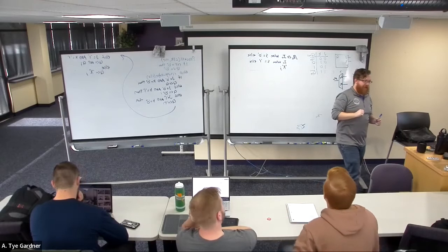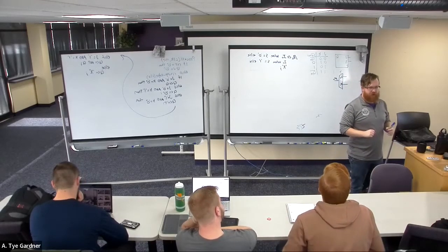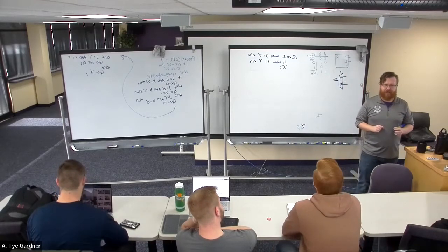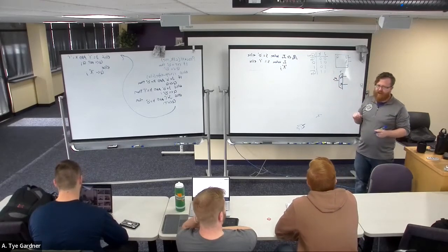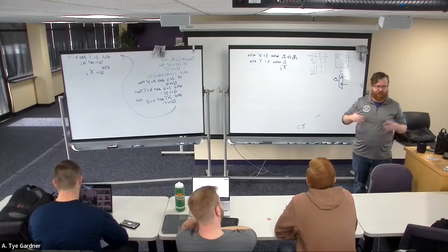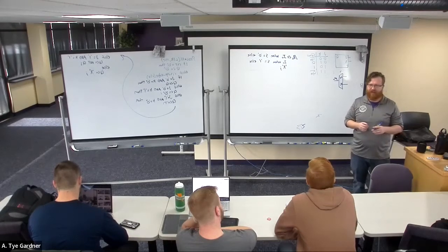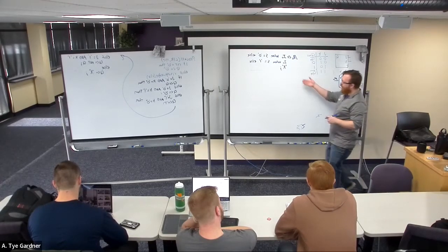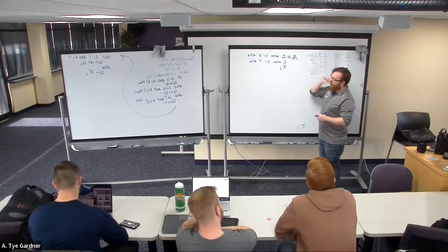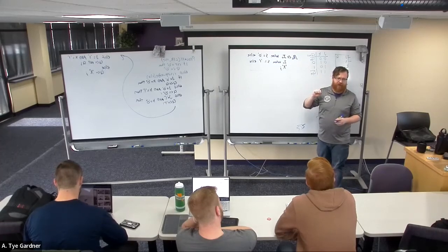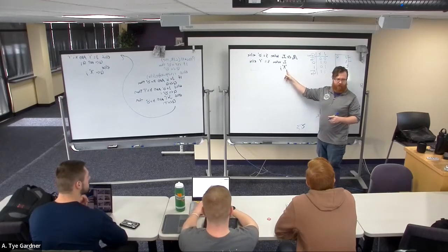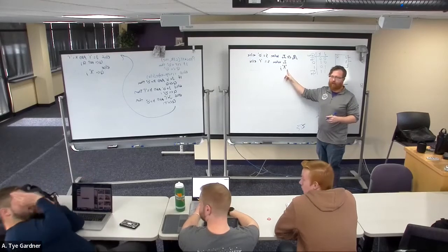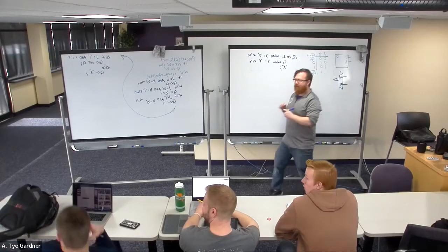VHDL formatting is not like Python if you've been taking 1400, right? Python is very particular about its spaces and its tabs. Whereas in VHDL, you can kind of throw tabs and spaces wherever you want and it will let you get away with it. However, do this, because when I write instructions in your project that say something like your code is well formatted, if you don't want me to deduct a point, do this, because this is well formatted, because this is readable.